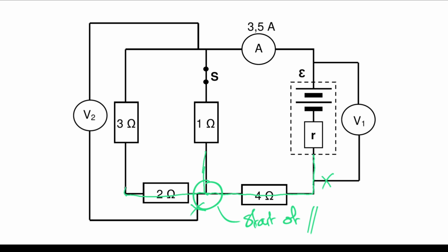And then here it travels along through resistors, through the switch. It hits another section over here, but it just goes back to the voltmeter. No current through a voltmeter. Yay!